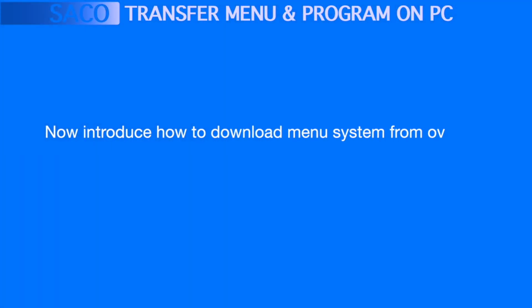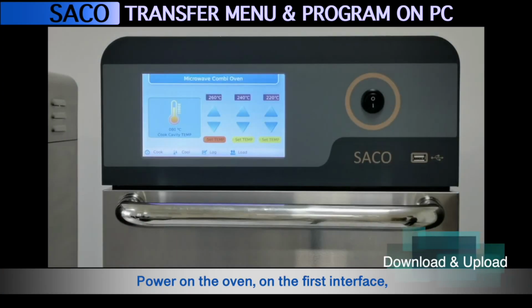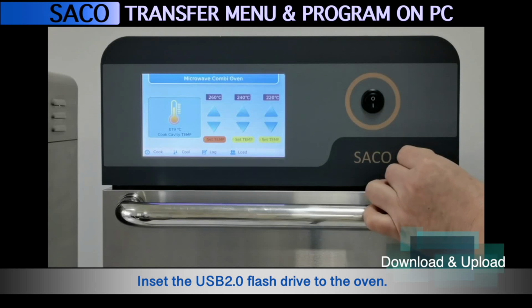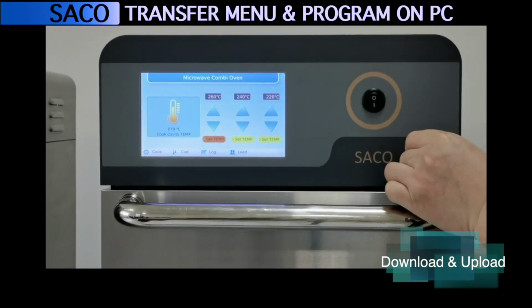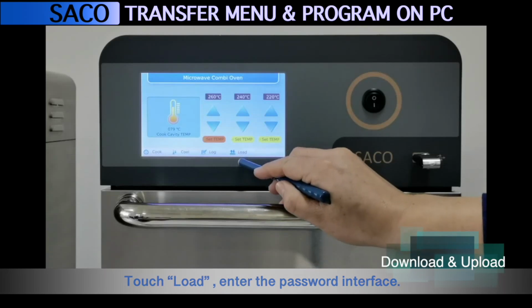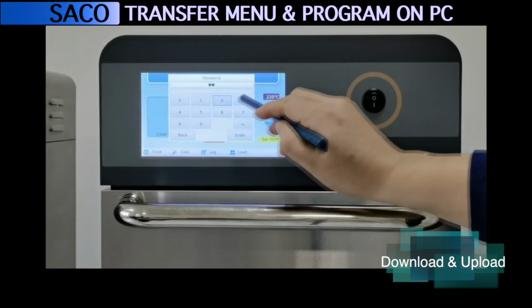Now, introduce how to download menu system from oven to USB 2.0 flash drive. Note, the flash drive should be empty before downloading. Power on the oven. On the first interface, insert the USB 2.0 flash drive to the oven. Touch Load. Enter the password interface. Input the password to enter the load interface.